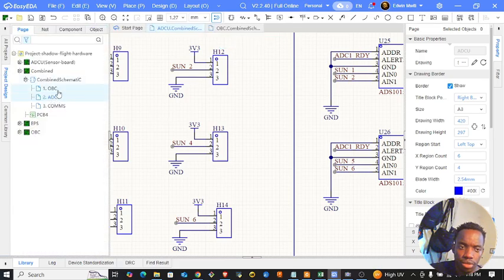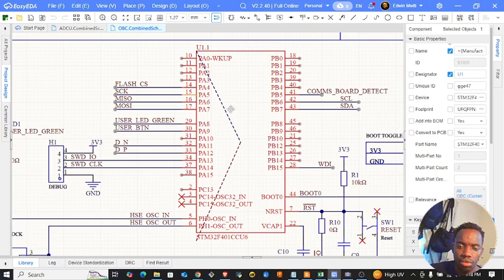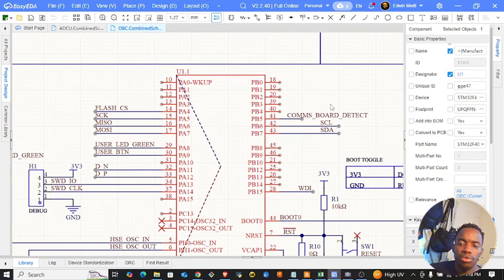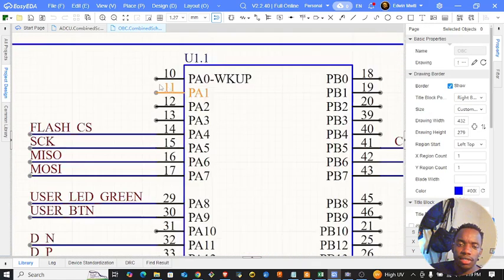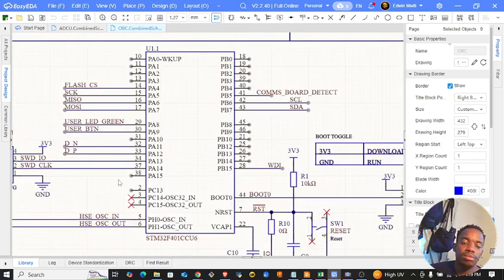So from this point to the OBC MCU, which is this one, and because they're giving you analog voltages, you need to use the ADC converters, right? But if I use that, I'll have 1, 2, 3, 4, 5, 6 pins gone that easily.